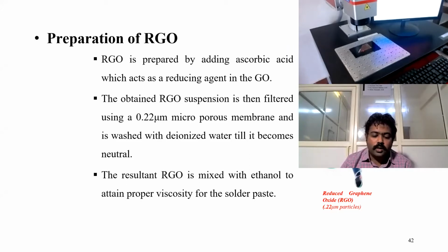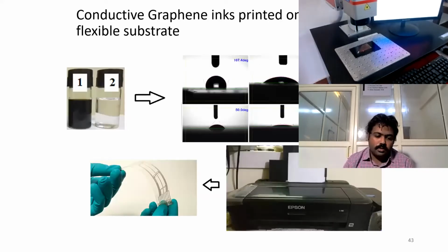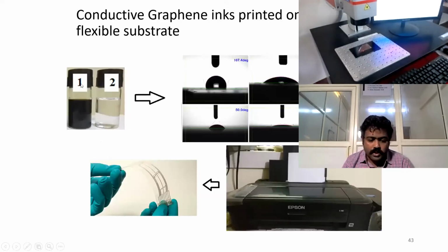So what we really need is a fine, porous, liquid part with good viscosity of ink. That will be done using these 0.2 micron to 2 micron filters, so very good nanoparticle inks can be made. That ink is very adhesive to any type of substrate, and can make very good conductive layers. This is one of the materials we made as a positive and negative. This is how the ink spreads out when it is initially dropped.